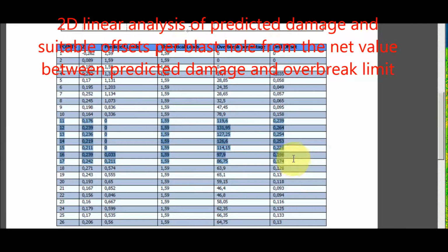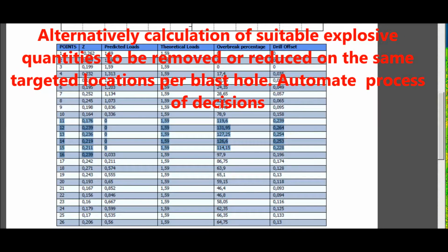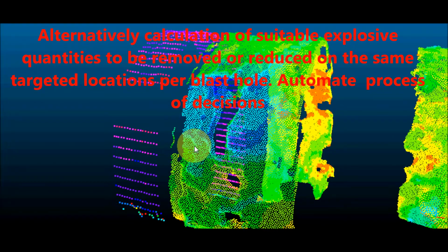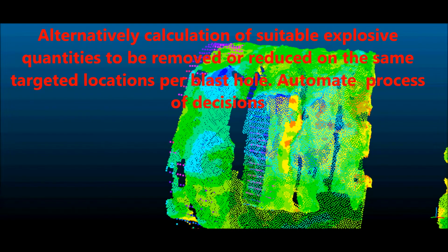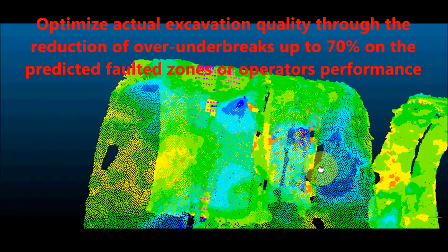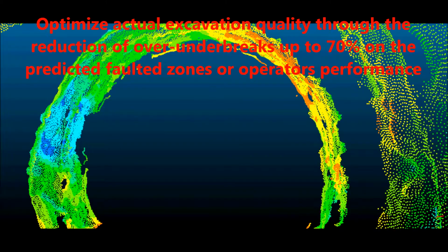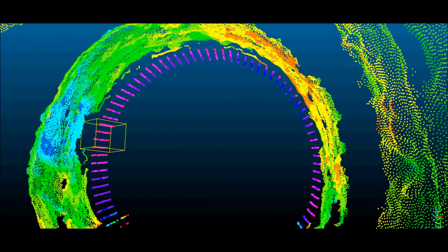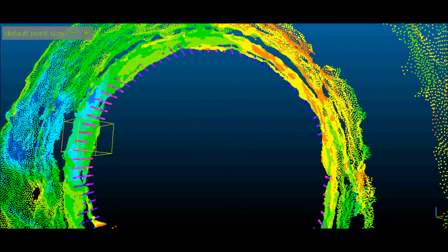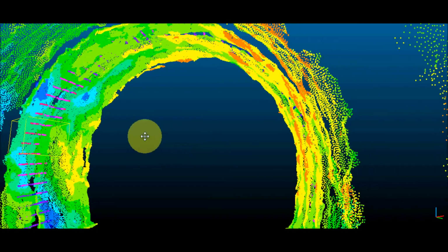The system uses learning algorithms in order to calculate and determine the effect of damage influenced by each parametric blast hole and corresponding rock type. Hence a 3D nonlinear statistical model, constituted by virtual x, y, z points, represents each upcoming damage based on the geologic and topographical survey of excavations. The predicted model is used for linear definition per blast hole, and thus the suitable blast hole position or explosives weight can be accurately established.